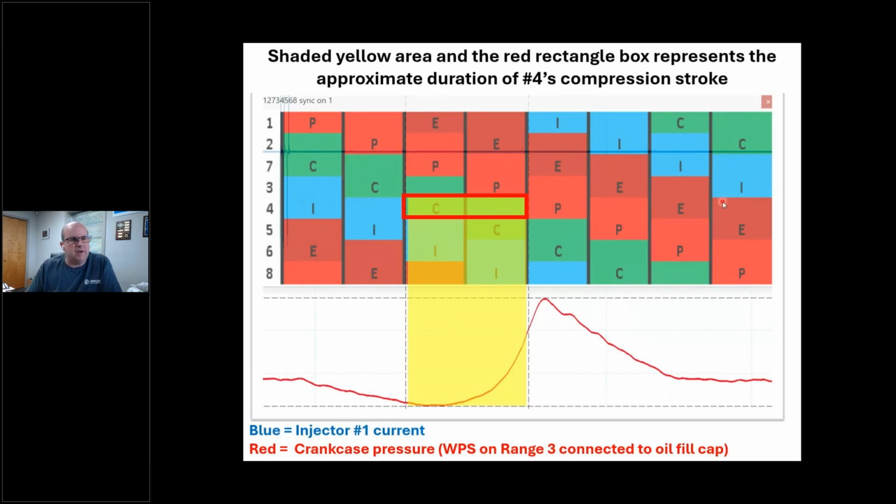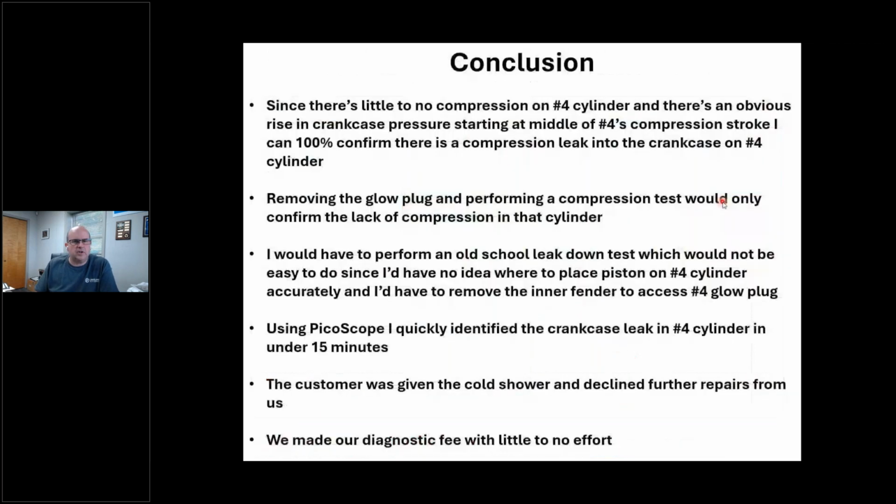Is this a leaky intake valve? Is this a leaky exhaust valve? No. This thing's got a short block problem, okay, or a blown head gasket to the crankcase, I guess. But it's chipped up. We know the story. It's got performance modifications. It's got a cracked piston or whatever. So we inferred that we can tell our customer, look, we know number 4 basically has nothing.